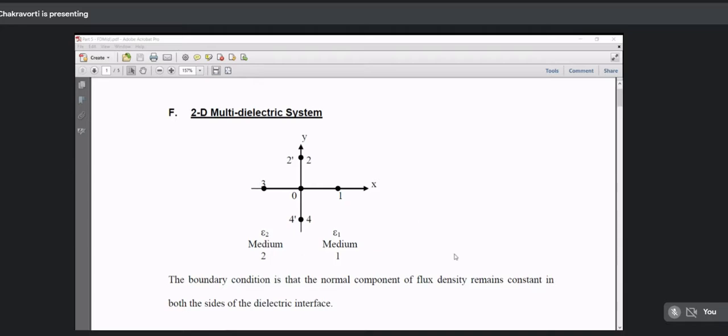Once we do that, we also have to remember that since there are two dielectric media, I cannot solve one Laplace's equation, because the potential function has a discontinuity on the boundary, or in other words, we have two potential functions. On medium 1, I say the potential function is V. On medium 2, I say the potential function is V prime, with the boundary condition that on the boundary, the potential must be the same, because you cannot have two different potentials at one point on the boundary.